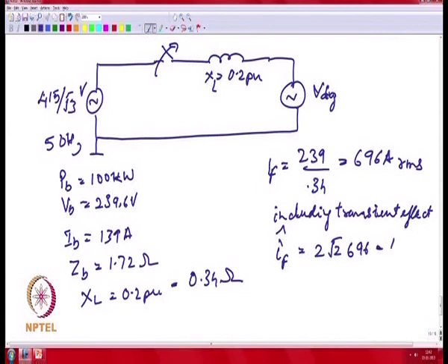So, you are talking about 2 kilo amps that can actually flow out when you have a dead short on the grid, and your switch S takes a finite amount of time to open. So, before it opens, you might end up with a fairly substantial peak current.